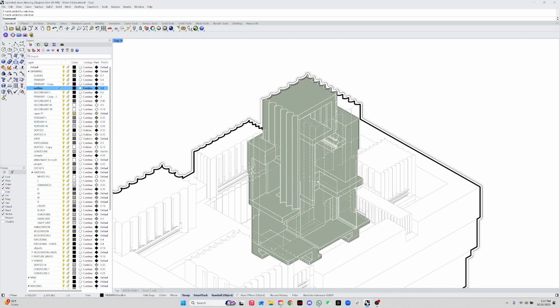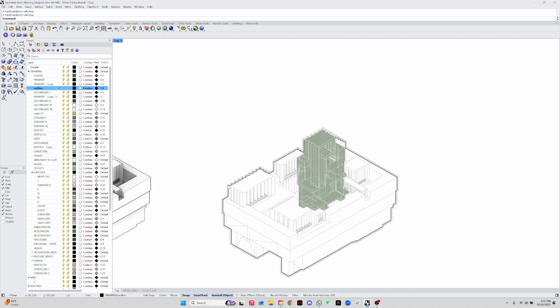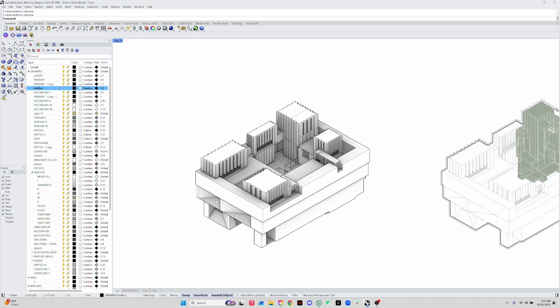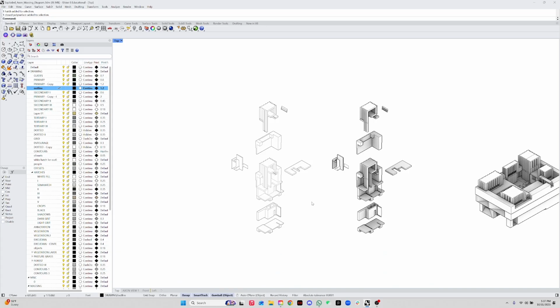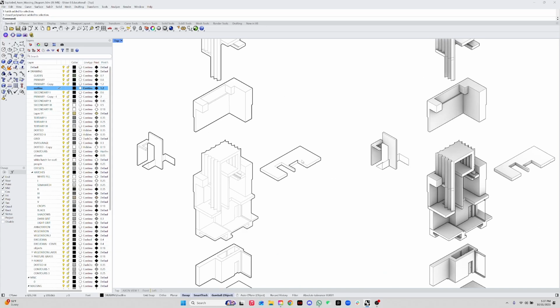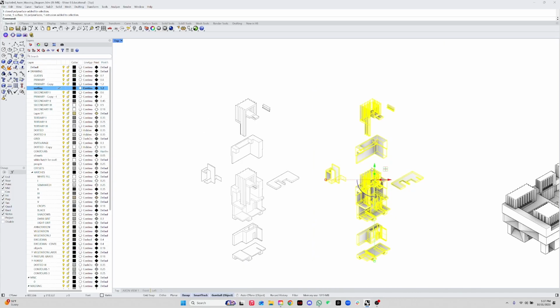So, to the right, to go back to why I'm doing it in the top view at a 30-60 degree angle: it's because I want to be able to add hatches, and that's what we're going to go over here. To make 2D some hatches, you have to explode them. That makes the drawing more heavy. So what you do is you have the model turned into a 30-60 in the top view.